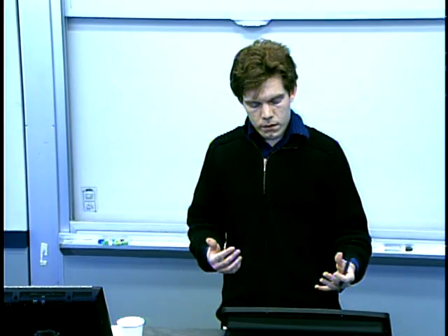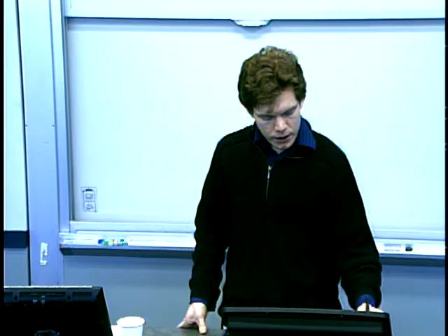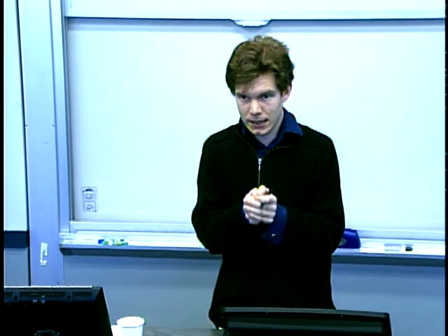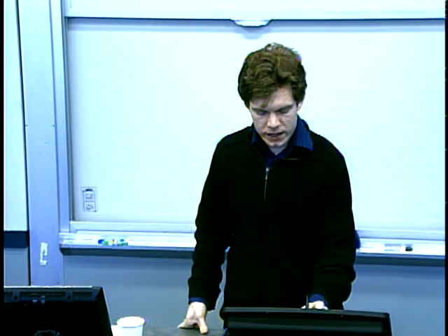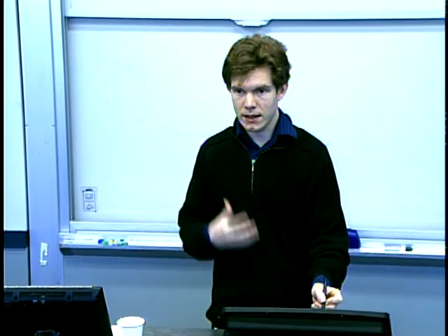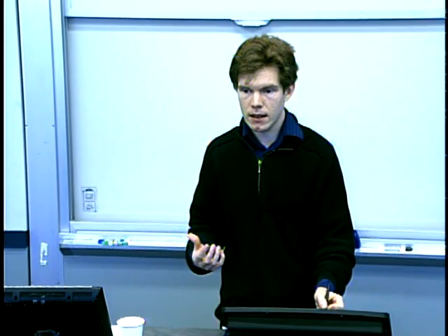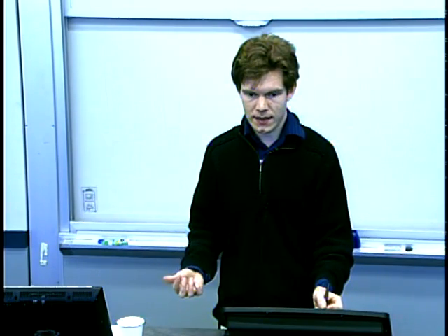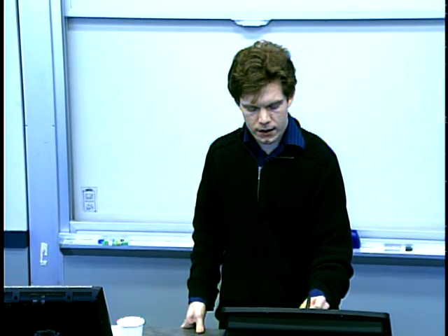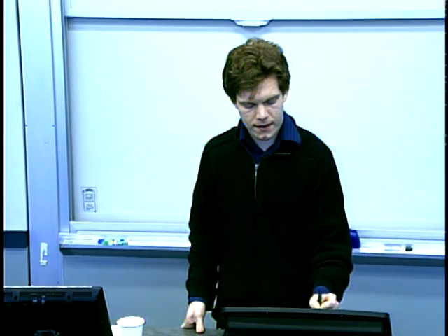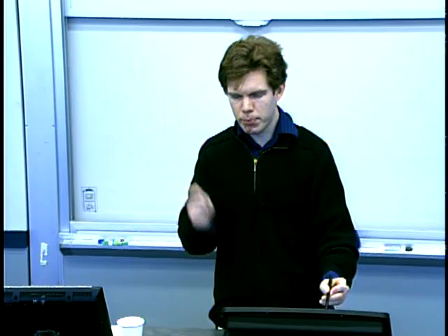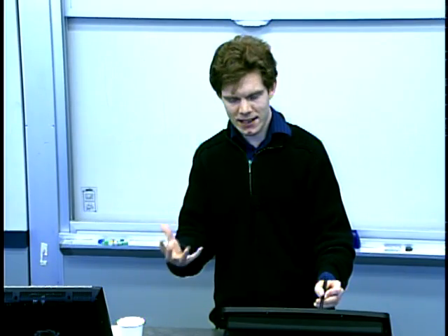So that relationship is clear, but then if we look within each chip, at the features near this 5% local metal density, we see this amount of variation. And if we look in the region where there's a much higher metal density, therefore less of the metal is being etched away, we see that the resistance is higher. And I'm sorry, by pattern density we mean the proportion of the chip that is open for etching.